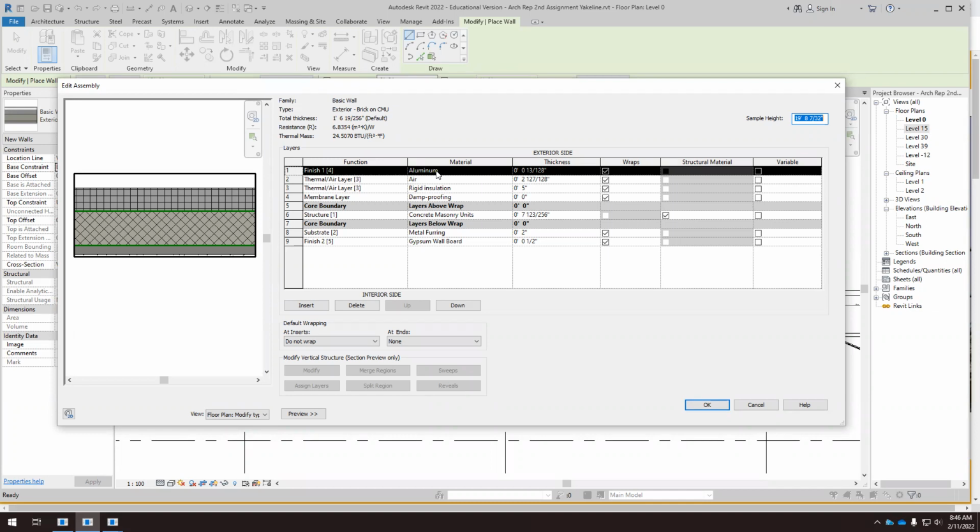We start the complete masonry unit again. And it's very important that we continue, we don't interrupt the thermal insulation. So we extend the thermal insulation this way, so that here we don't have the thermal bridge. If we interrupt the thermal insulation because we have a steel structure, there will be a lot of issues. So now we have to place the complete masonry unit, the steel structure, to make sure that the thermal insulation is continuous outside the building.